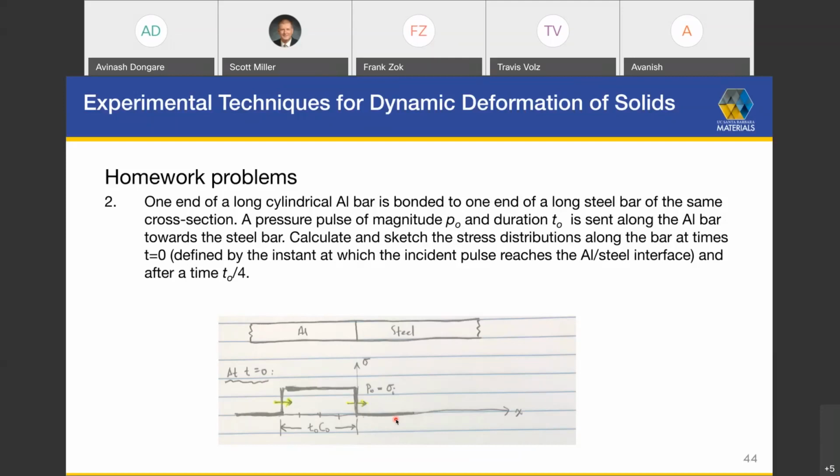Now, one additional, somewhat complicating element is this. If we do this as a Kolsky impact test, so let's say we were to strike the aluminum with some other bar and put a stress pulse into the aluminum. Recall that we're assuming here that we have one-dimensional stressing. But at the contact between the striker and the aluminum, because of the Poisson straining, you have a certain amount of radial inertia. And that causes release waves to be generated from the external surfaces going into the aluminum. That then gives rise to oscillations in the overall stress strain curve.